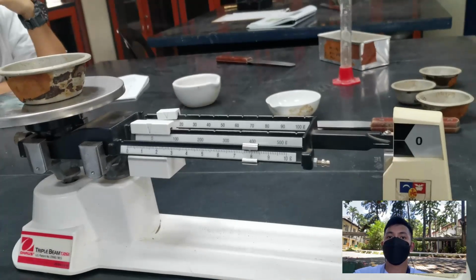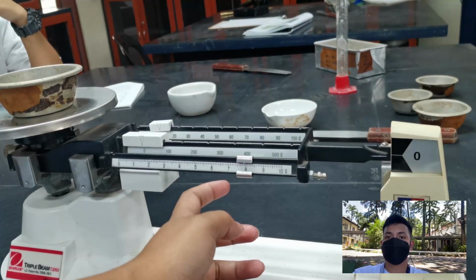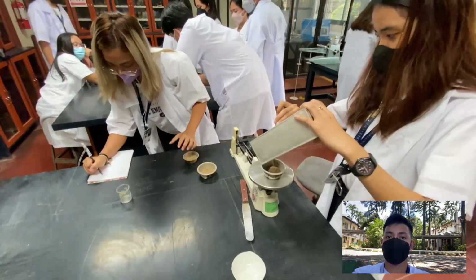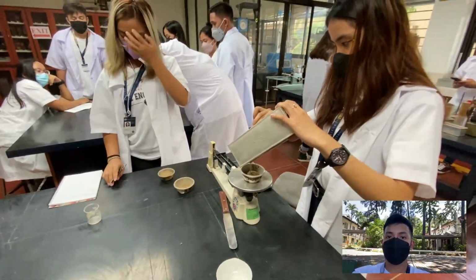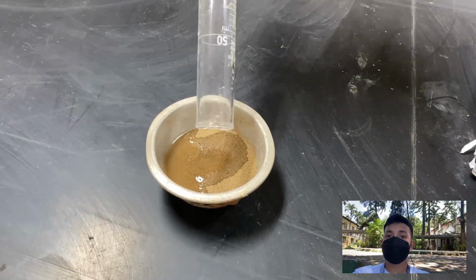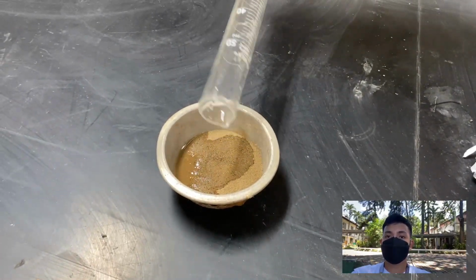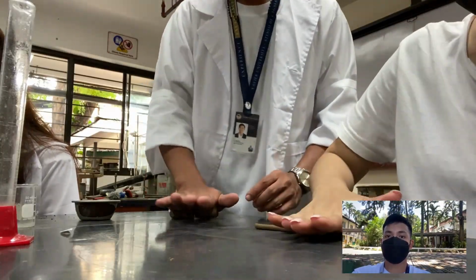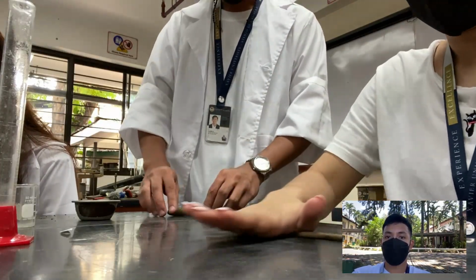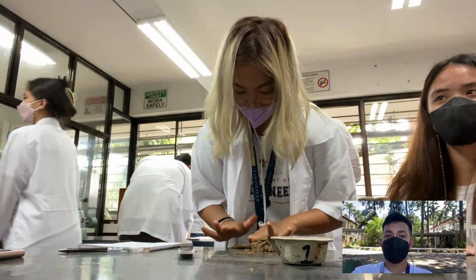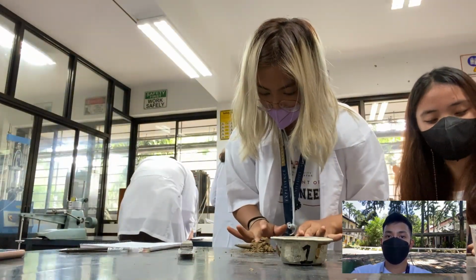First, weigh the remaining empty moisture cans with their lids and record the respective weights and can numbers on the data sheet. Second, take the remaining 1/4 of the original soil sample and add distilled water until the soil is at a consistency where it can be rolled without sticking to the hands. Third step, form the soil into an ellipsoidal mass. Roll the mass between the palm or the fingers and the glass plate. Use sufficient pressure to roll the mass into a thread of uniform diameter by using about 90 strokes per minute.